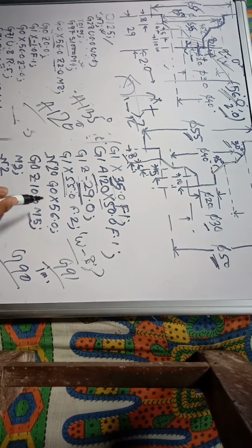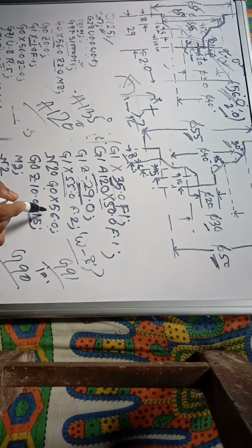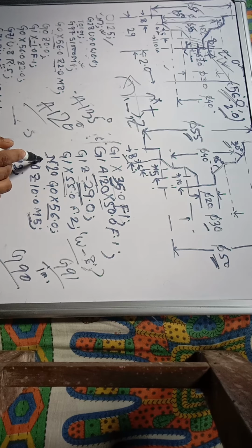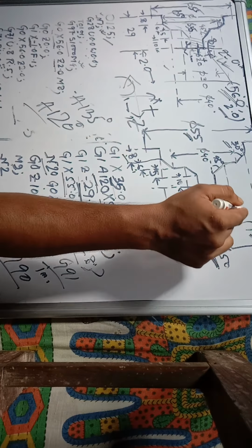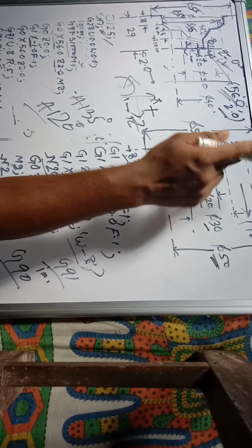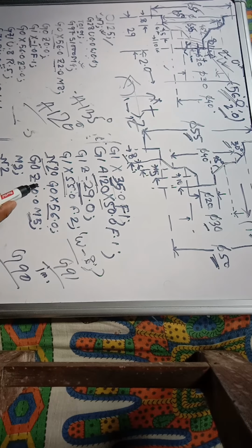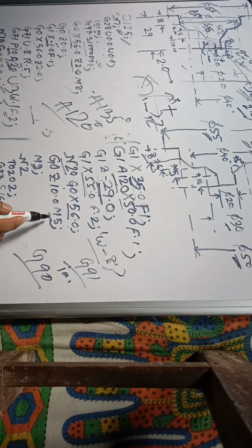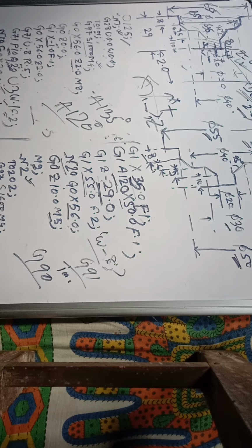After the finishing of this, it will reach the maximum diameter, and that is also the end of the sequence, which is represented by N20. After that it will move away from the job by a distance of 10 so that it will reach the home position. After that the rotation of the chuck will be stopped, and the coolant will also be stopped. Then we may use tool number 2 for the finishing cycle.